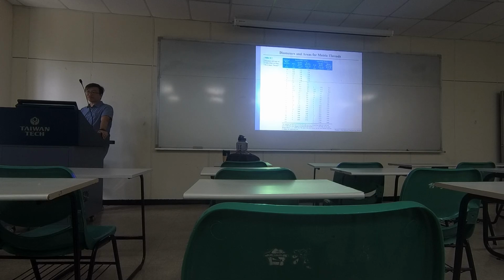If you want to know how much tensile force you can apply to lengthen the thread, it will let you know, okay, the stress area, you should use this number, okay? So it's not the area computed from any diameter. I think they use experiments to estimate this stress area.